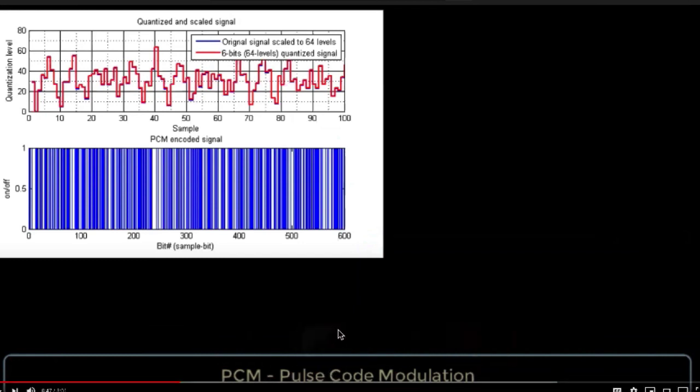What pulse modulation means is, remember, the computer is very fast. It can push from 0 to 5 volts in a very fast sequence. So in making the vibration of the air, it doesn't have to use the negative side. Remember last time we talked about how when you push the positive side, the cone of the speaker will push out, and when you have the negative, the cone of the speaker will pull back. So you're doing this vibration to generate the sound.